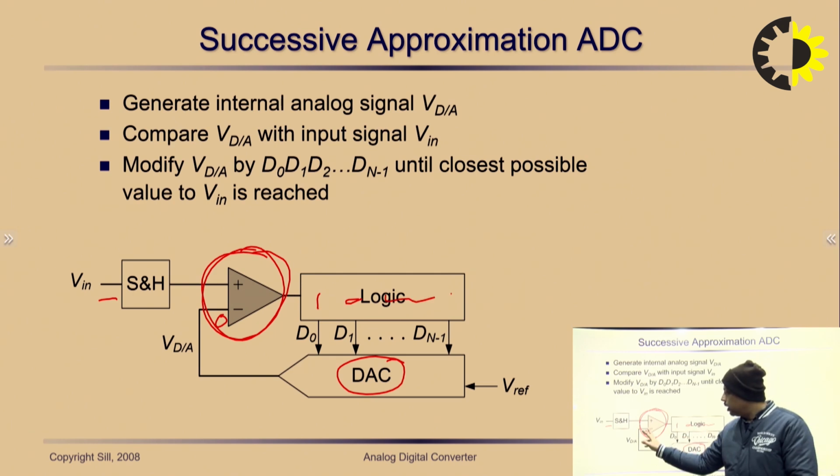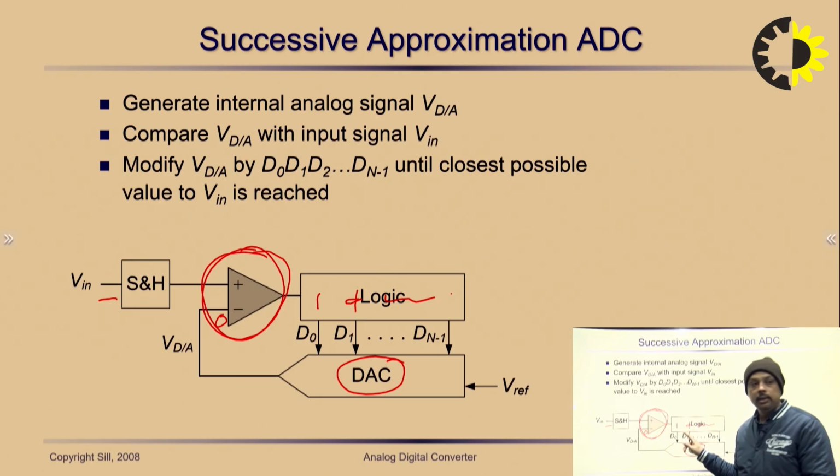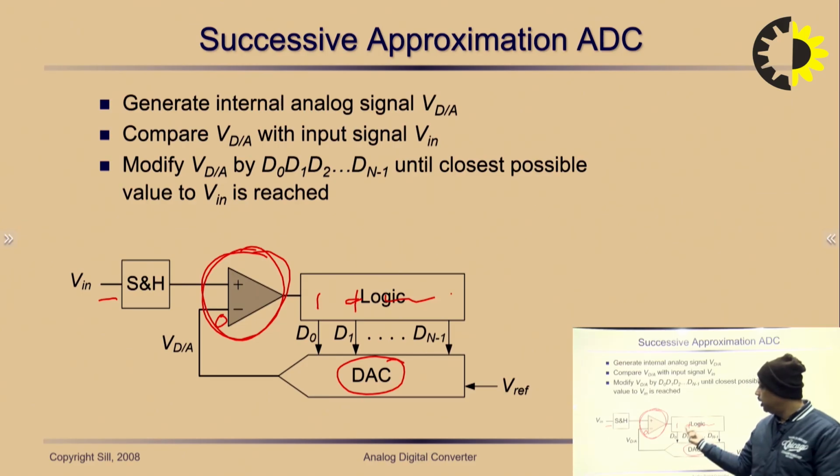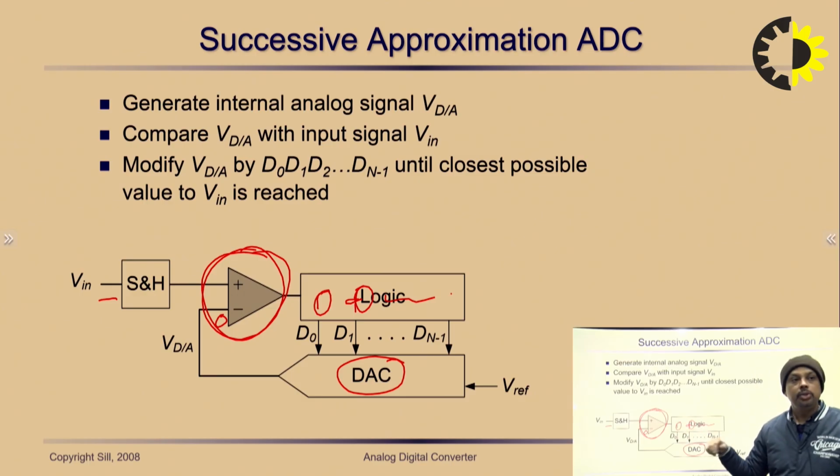Again it compares the value with this new data, and if it is again 1, then it is going to set the next bit. For n bit output, n cycles are required to set all the bits. If the comparator output is low, then that bit becomes 0, or in the case of the initial one, it must become 0 if it is lesser than the previous one.